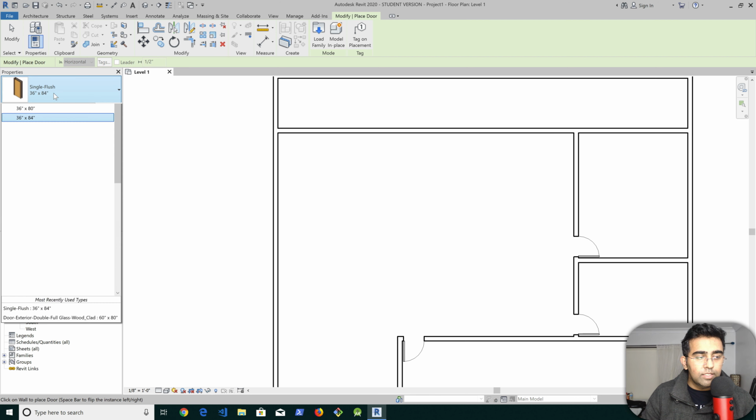And I'm just gonna open that inside. So let's just put it here. All right, so now we got the doors. Now here we could create some rooms, or we could create something. So what we can do here is maybe just click, and then we can just move this door right here. And then I'm gonna click on the wall to create a wall actually.